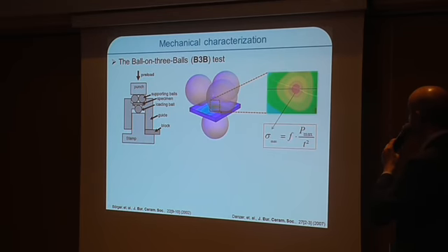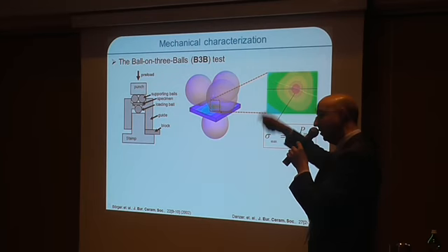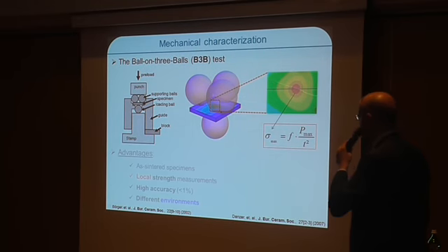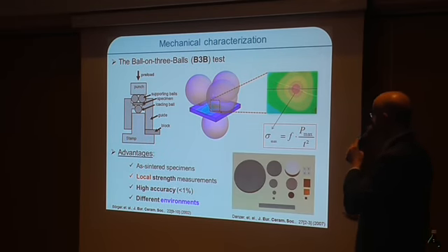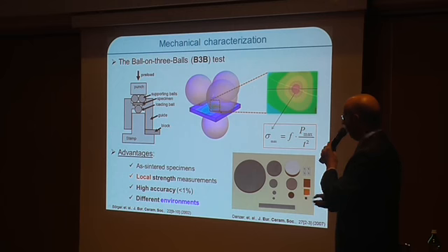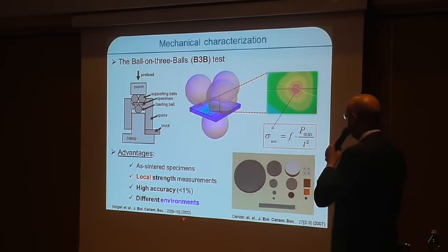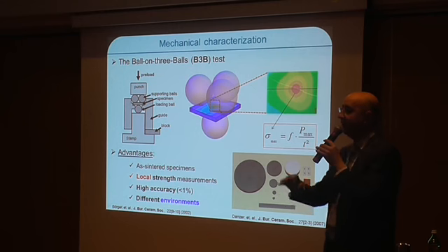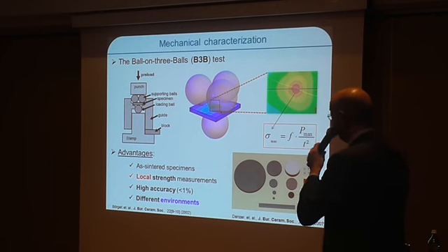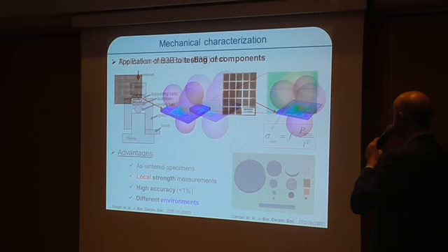And you can compute a little bit and find out what the maximum stress is, and then you make some Weibull plots and so on. It has many advantages: we can make local strength measurements, if we want to, in certain locations, it's very accurate, and you can put the whole thing in different environments and see environmentally assisted cracking effects, for instance.